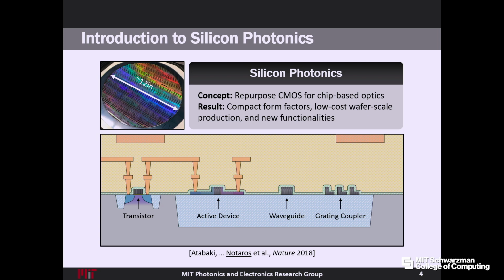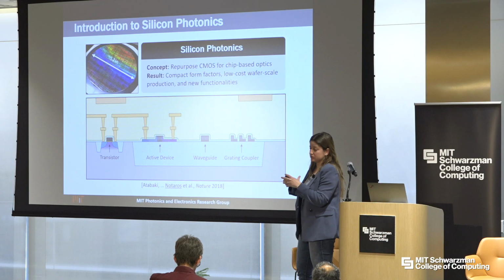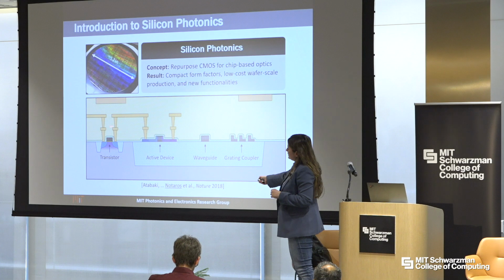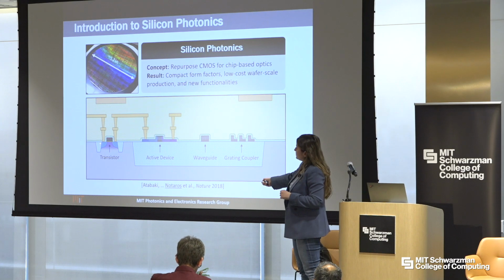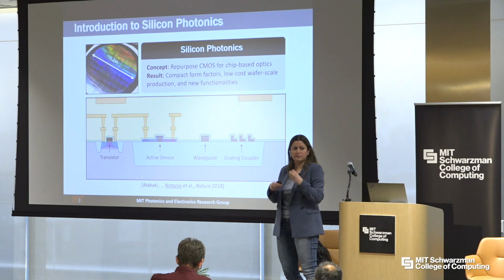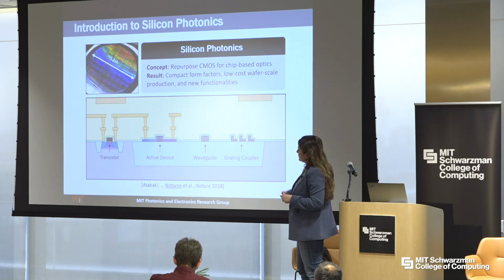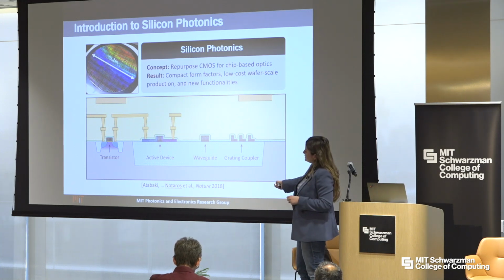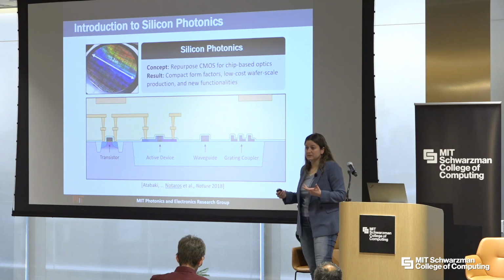So you'd have a silicon layer here. This is if you took your computer chip, for those of you that are maybe not as familiar with the hardware side of things, and you cross-section it in half, this is what one of these little nanoscale transistors would look like. So you have the silicon over here. Then you would have regions of what's called doped silicon. That's where you take the silicon, you bombard it with dopants. And then you'd have metal coming down into contact with those doped regions.